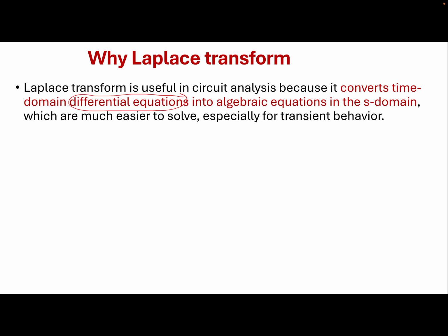My equations are going to be reduced to simple algebraic equations, and I can easily solve them. I'm going to use these Laplace transform analyses to solve RC, RL, and RLC circuits and understand their transient behavior. Maybe we will do some examples very similar to ones we have solved in the past with time domain analysis. Now we can do it in the Laplace or S domain as well, and we can compare the results. The results should be exactly the same.